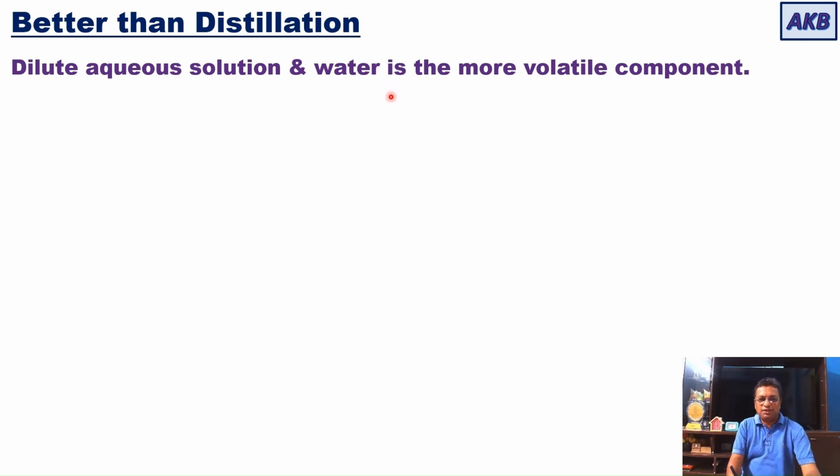So in applications where components are to be separated from dilute aqueous solution and water is the more volatile component, you'll find that liquid extraction is better than distillation.